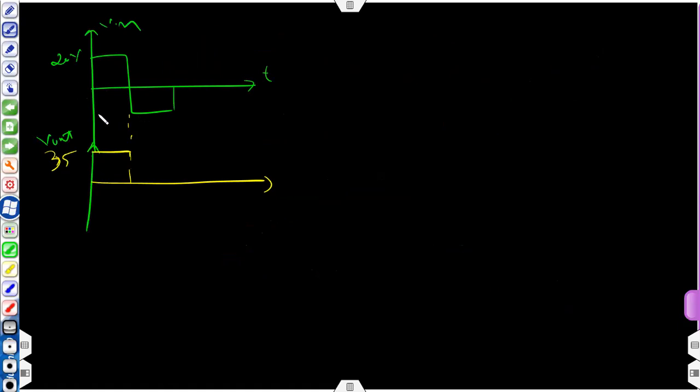So for this minus 20 volt, you will get minus 5 volt. And the short check, just add the positive side value and the negative side value. 20 and 20 gives you 40. Similarly 35 on the positive side, 5 to the negative side, so 35 plus 5 gives you 40. So this is how you can ensure that your answer is correct.